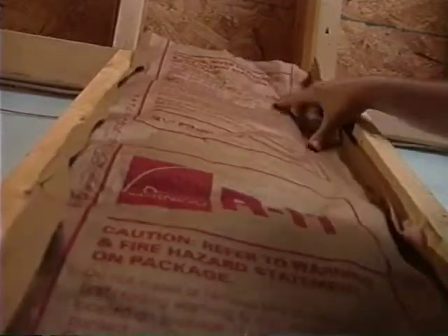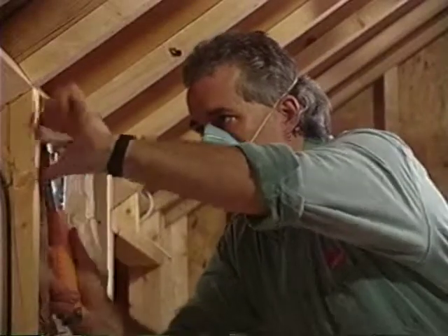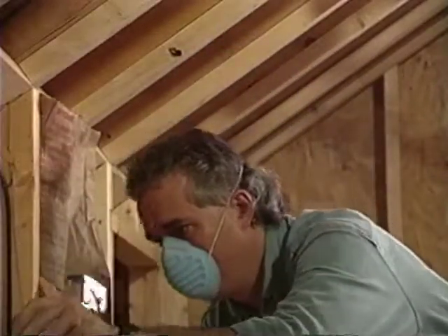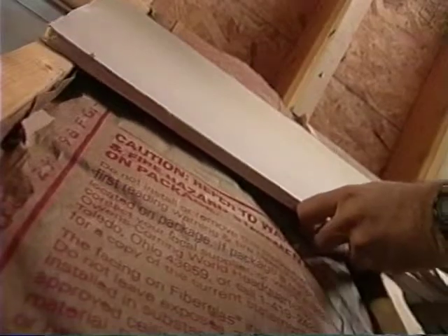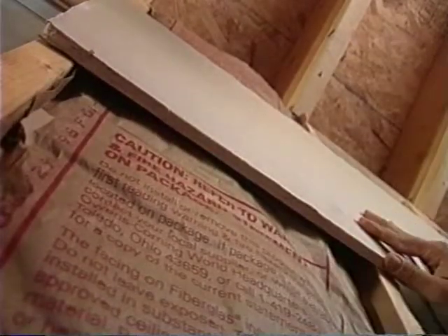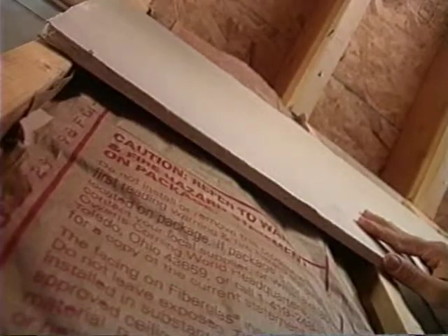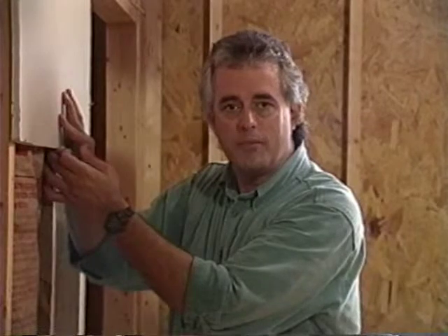Let's install some paper-faced batt insulation in a wall cavity to illustrate how misalignment can happen. We are using a side stapling or inset stapling technique to install our batts. Let's take a look at what happens when our sheetrock contractor comes along and installs his sheetrock. With the inset stapling, we're still going to have air gaps here in the corners, and gaps are something that we're always trying to avoid. These gaps will allow air to flow behind the sheetrock, and this may create either comfort problems or a potential source for moisture problems down the road.